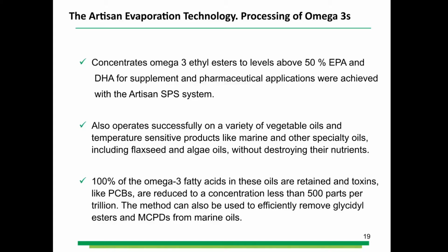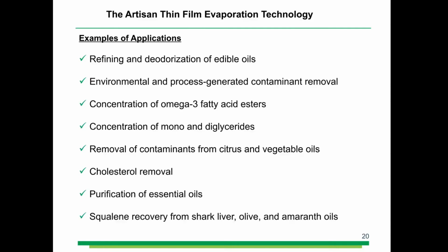100% of the omega-3 fatty acids are preserved, and as an added advantage, as mentioned before, the multistage Artisan evaporation system is used to remove glycerol esters and MCPDs that are also found in some marine oils. The new Artisan multistage thin film evaporation technology has been successfully applied in several other applications.